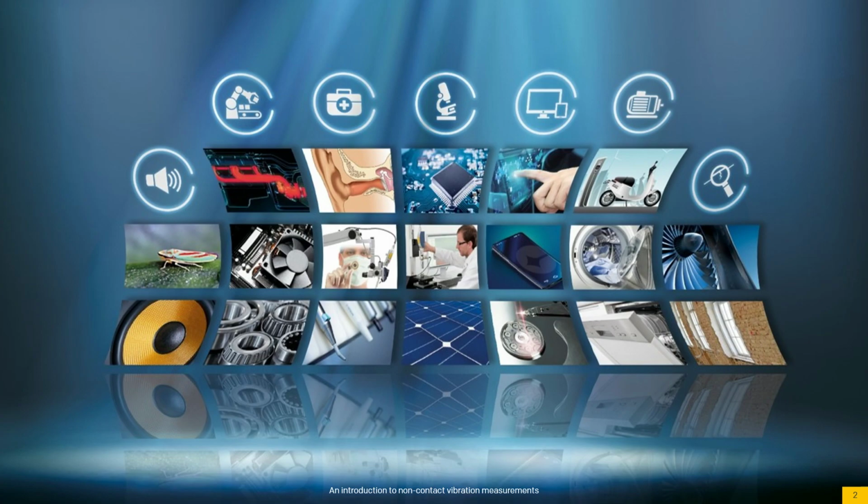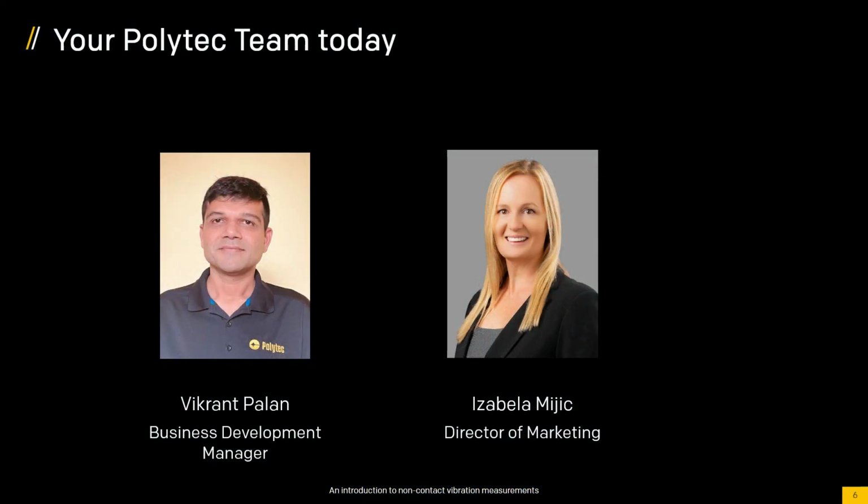But let's go back to the basics. The scanning vibrometer has two mirrors, the X mirror and the Y mirror. The X mirror is plus minus 25 degrees, so 50 degrees total. The Y mirror is plus minus 20 degrees, so 40 degrees total. So 50 in X and 40 in Y. You can imagine that the farther away you are from the sample, the more area you can cover. The closer you are, the smaller the area, because of the cone effect.